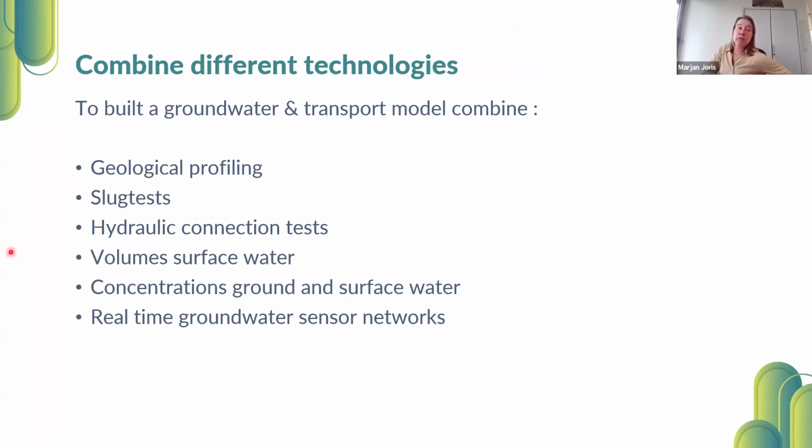So iFlux measurements are also often used to validate groundwater and transport models. And then this information is combined with geological profiling, slug testing, hydraulic connection tests if there are several different layers present, volumes of surface water and concentration in ground and surface water, and real-time sensor networks. And this will bring us to the next topic, the real-time groundwater sensor networks.